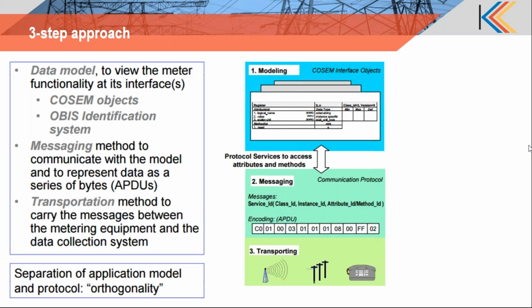The reason is, as I explained earlier in answer to one of the questions, that DLMS has only 2 mandatory objects, which have nothing to do with metering. They are the current association object and the logical device name object. If only these 2 objects are present, the manufacturer can still get a DLMS certificate. So the DLMS certificate does not ensure the utility or the end user who is going to use that meter in their project that it will meet their system requirements, that it will generate the necessary data in the standard format, ensuring interoperability. Those things cannot be guaranteed with the DLMS UA testing.